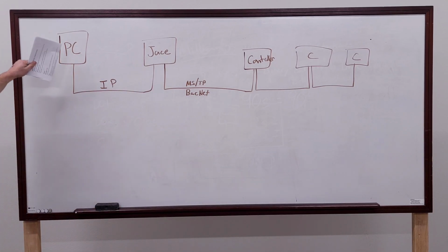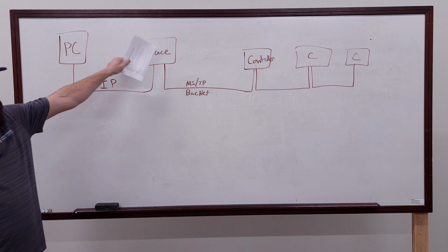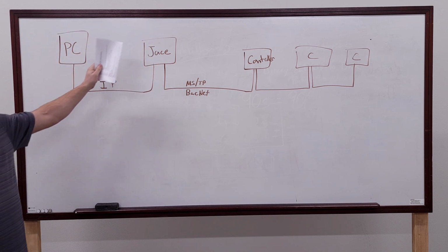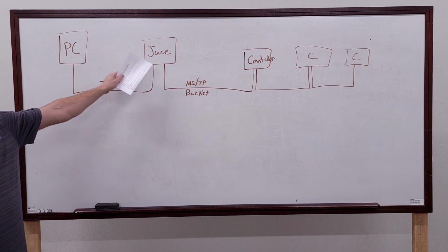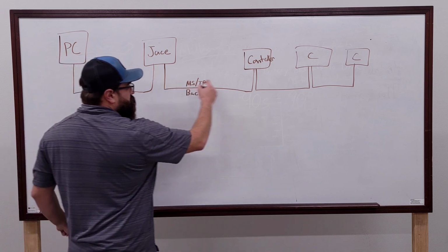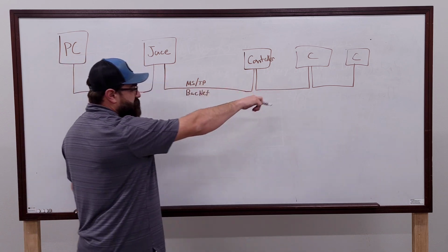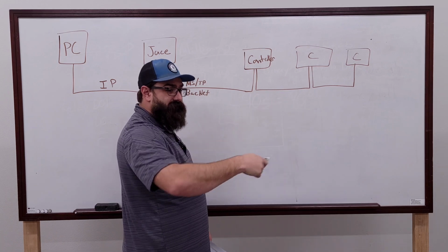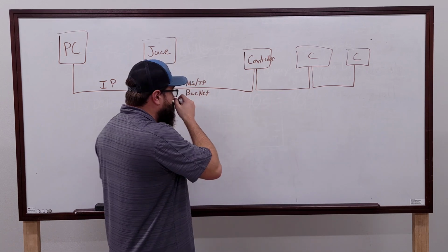This guy doesn't really do anything. This is just an interface. This is what allows you to pull up the graphics that are in here, the points that this is reading, and so forth. This guy talks to all your field devices over the MSTP network and gets values from each of them and sends them commands and values.